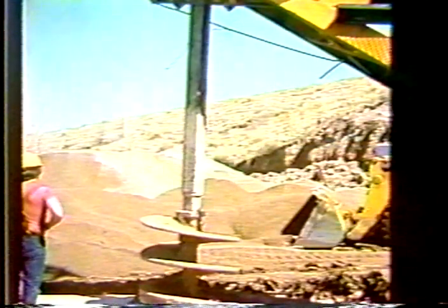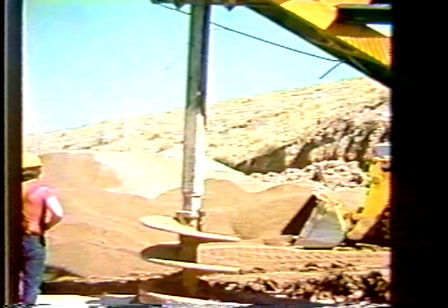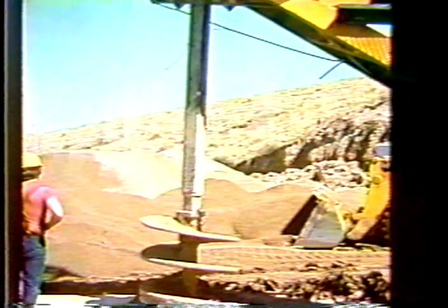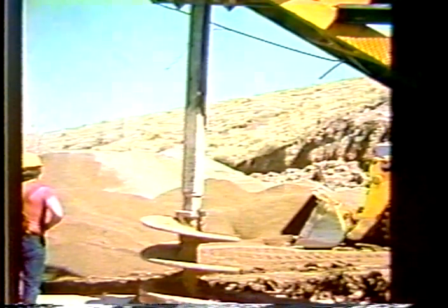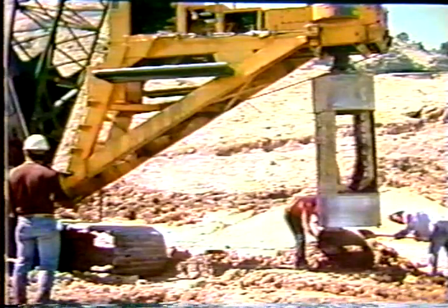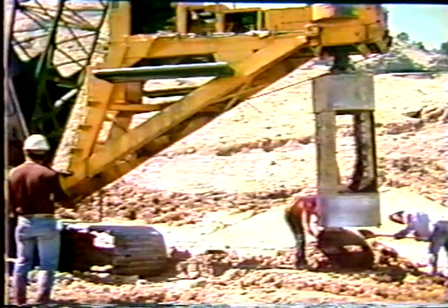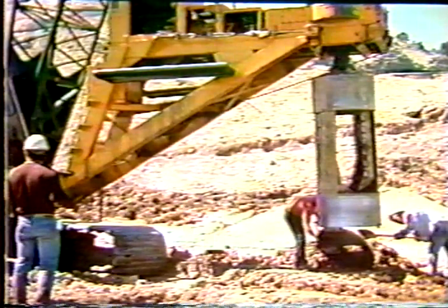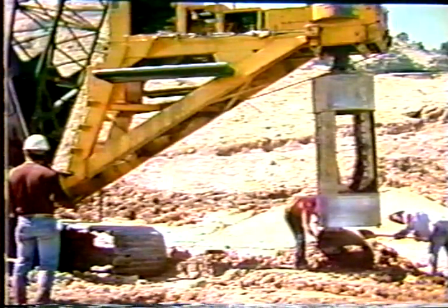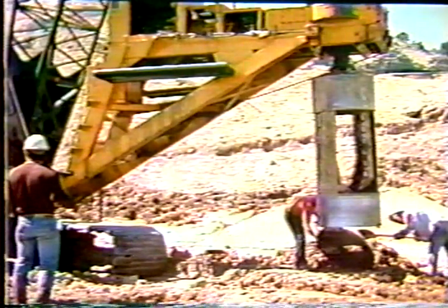Let's just take a look at how these vertical wells might be installed. They use a special drilling apparatus, or one that's used for drilling caissons. The diameter of the auger there is about 2 or 3 feet, and they simply drill a hole in the ground, and when they get down to a certain depth, they use what they call a belling tool. This device has arms that swing out when they drill down, and at the bottom of the hole, the arms start swinging out, and they bell the bottom. They cut a bell-shaped groove. Then once they do that, they backfill with sand or gravel.